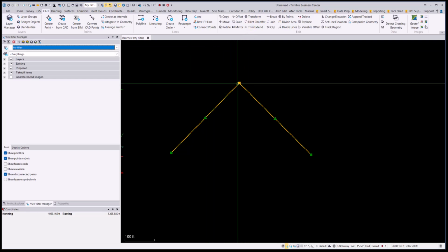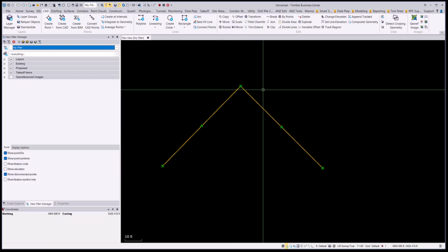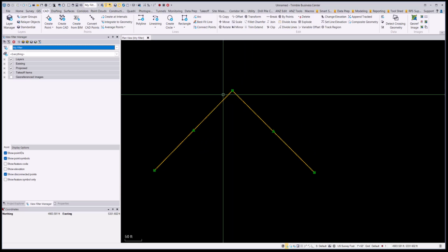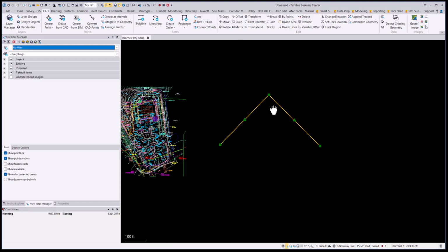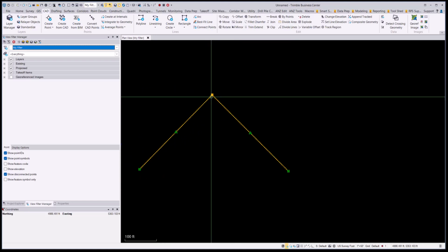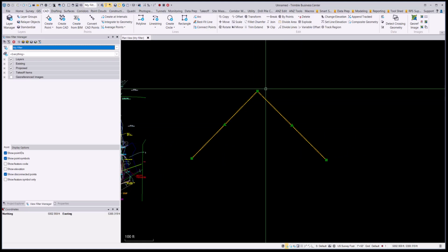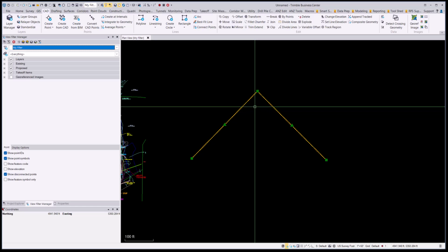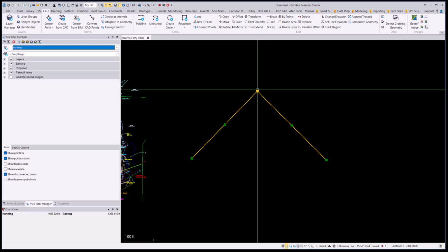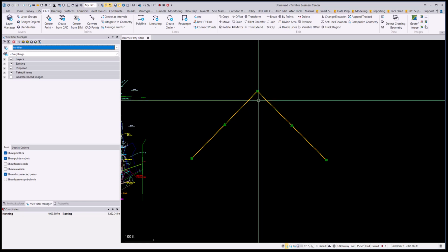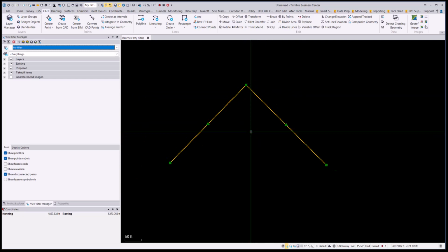And you know, if we are doing this for data prep, this is a must for me in data prep. Maybe not so much in takeoff because you're trying to get the takeoff done quickly. Accuracy could go out the window a little bit. You know, you're just trying to get a good number, and a little corner like this isn't going to adjust that number all that much. But in a data prep world, this is important. And also in a data prep world, you got to think if this was a curb line and that curb line was going to like a curb machine, I don't want to have little segments that are gapped, and so you want to make sure these corners are nice and neat when you're doing something like that.